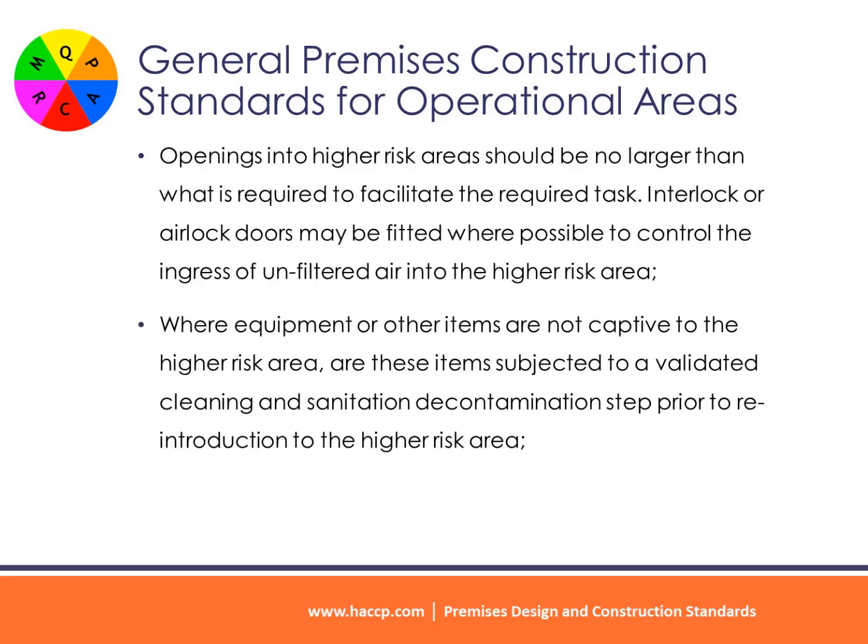Openings into higher risk areas should be no larger than what is required to facilitate the required task. Interlock or airlock doors may be fitted where possible to control the ingress of unfiltered air into the higher risk area. Where equipment or other items are not captive to the higher risk area, these items should be subjected to a validated cleaning and sanitation decontamination step prior to reintroduction to the higher risk area.